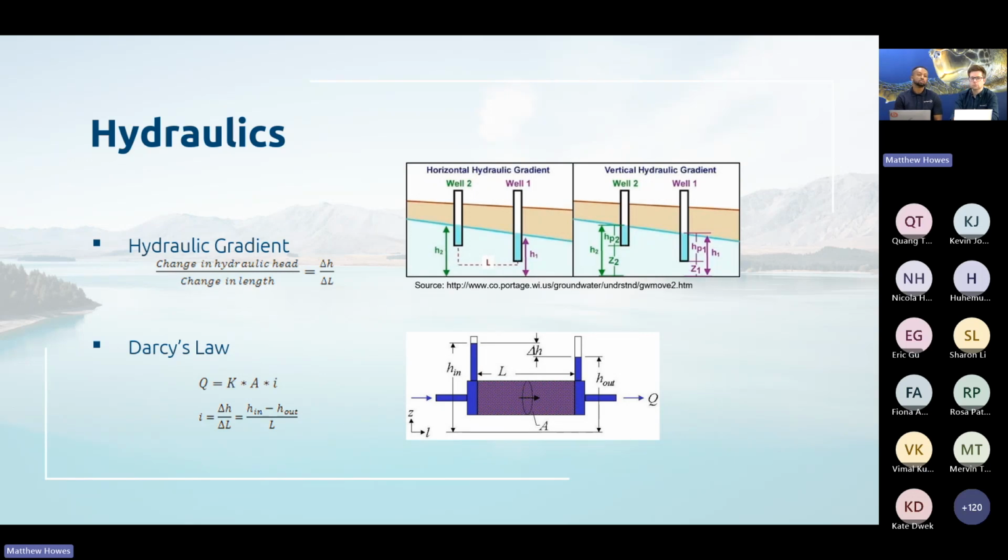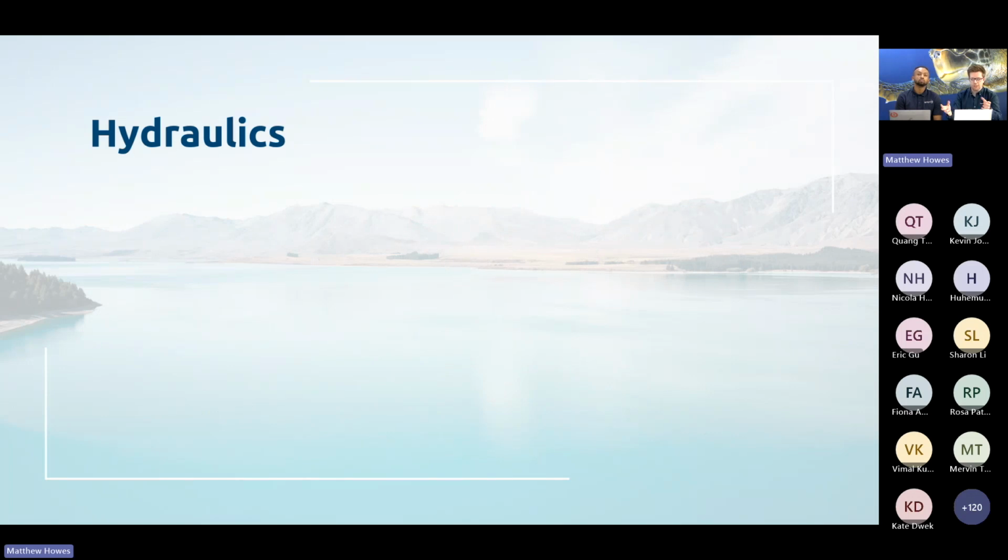So what that means is the higher the hydraulic conductivity, the more flow you can discharge through a porous medium, and this can be applied in rain gardens and also the filter. I'm sure most of you are familiar with that product, and also the storm filter. Right, it's nice seeing how Darcy's law draws together the continuity equation and the head loss as part of one concept. Yeah.